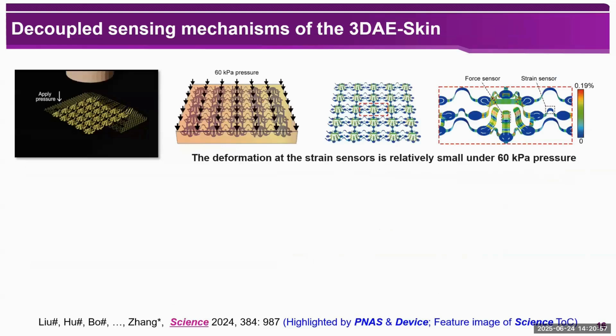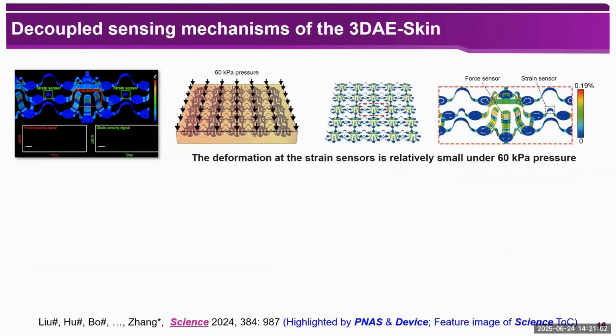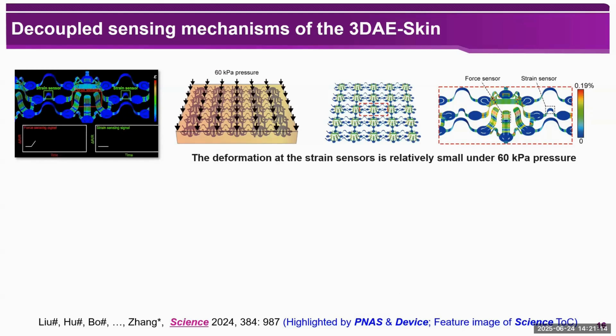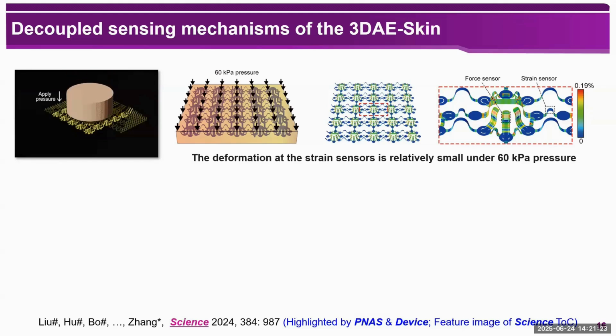And then I will use mechanics simulations to illustrate the decoupled sensing mechanism of the force and the strain. So if you look at the video here, we can apply a pure pressure loading to this device. And then you can notice that the deformations induced in these strain sensors are much smaller than those in force sensors because those force sensors are very close to the skin surface.